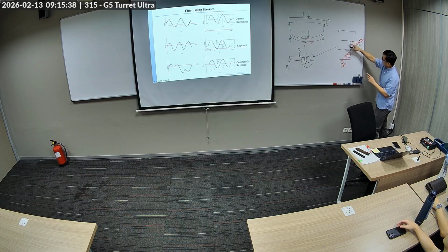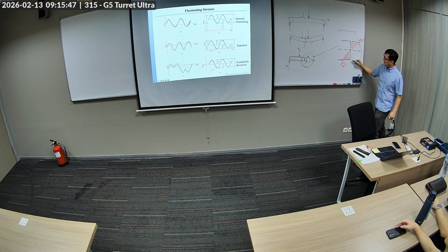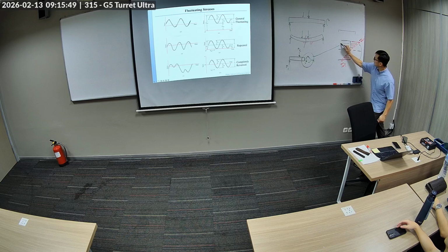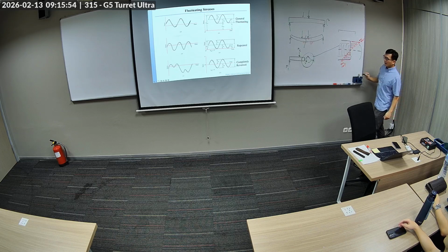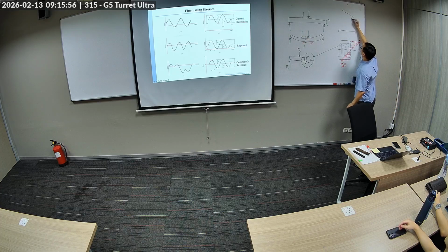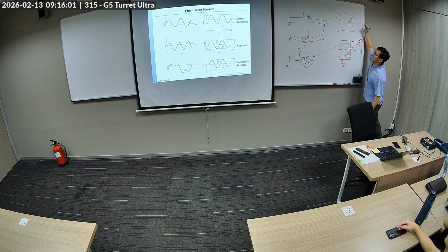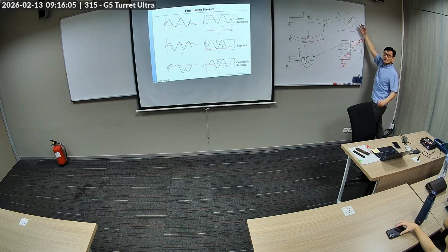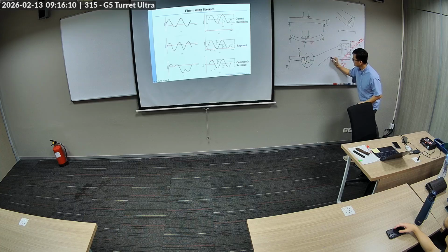You see that in this area, it's not doing much, not as much as the top and the bottom. And that's why we often make this hollow. So this is why you often see a beam with a hollow, and construction often uses hollow sections. Or maybe you have I-beams.